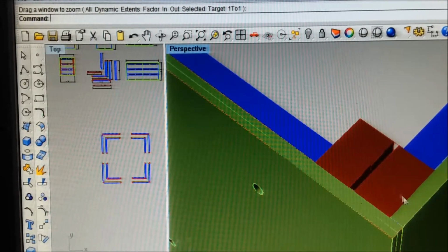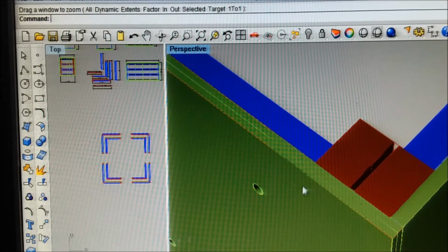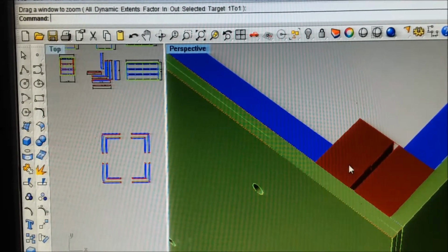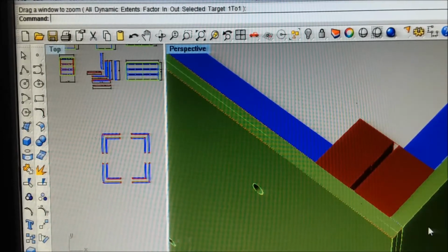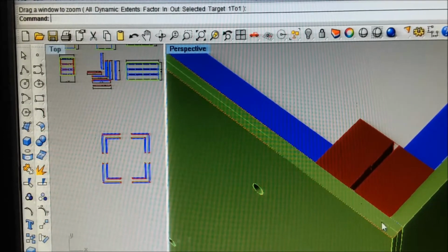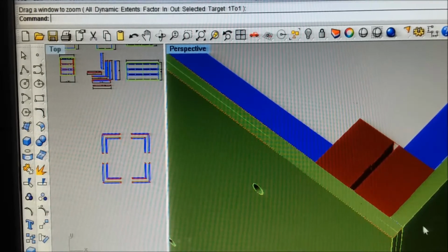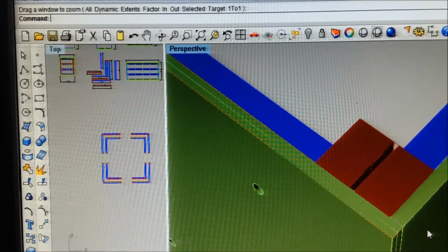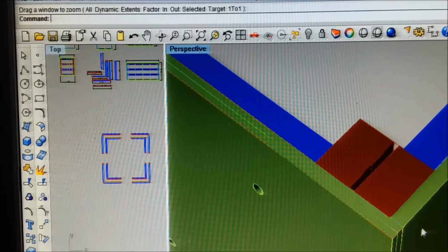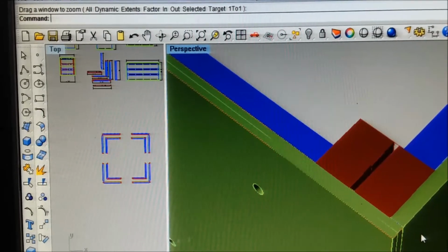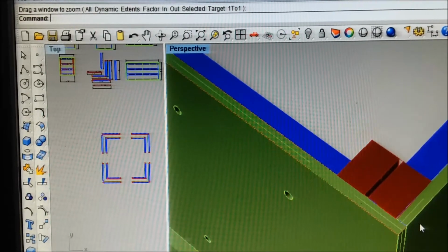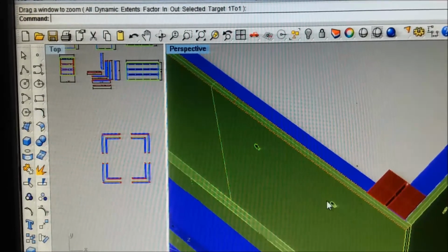This one is screwed to this phenolic board. This one's got screws in from this, and then the two of them bolt together. There are holes in this phenolic board for the bolt that goes through that. This bolt head is going to be a blemish on the concrete. We're going to put a piece of duct tape, maybe two strips, over it, and we're going to have to fill that with a little bit of render as a dab. But you have to put a dab in these.